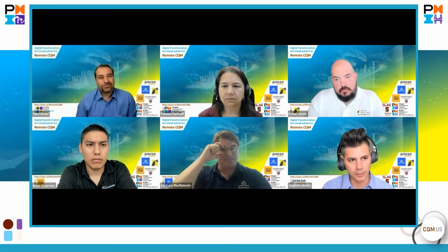One quick thing to add to your presentation, Zach, is that when you look at what Reconstruct is showing you, these point clouds and these 360 photos, it's important to understand the expeditious nature of how quickly you can come up with that. So, for example, Zach showed our project, the Federal Center in Denver for GSA. That was a 680,000 square foot building. We were able to capture that in 3 days and develop a point cloud from it. And that's from when we started scanning to when the point cloud is available.